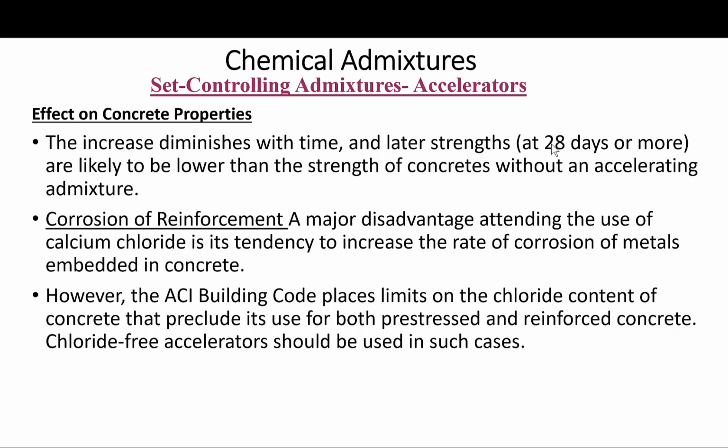However, the increases diminish with time, and later strengths, at 28 days or more, are likely to be lower than the strength of concretes without an accelerating admixture.